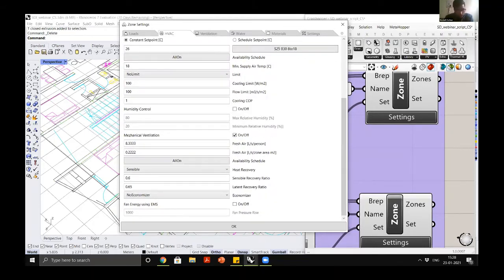The next part of that is mechanical ventilation. So essentially all these systems are modeled in a way that they also provide you fresh air and mechanical ventilation. Fresh air requirements can be modeled from ASHRAE standards or any other standard that you are referring. NBC will also give some requirements. But these are only for those kinds of systems which have a fresh air output.